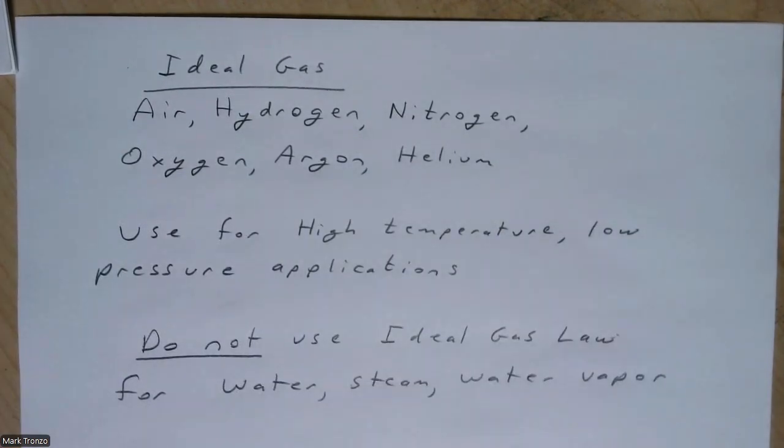You could possibly use it for steam applications if you have a very, very high temperature and very, very low pressure, but I would just get in the habit of not using it at all if it has water, steam, water vapor, etc. And never use it for a liquid or any kind of mixture.